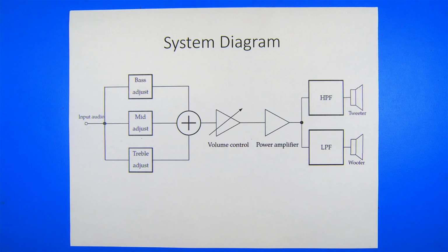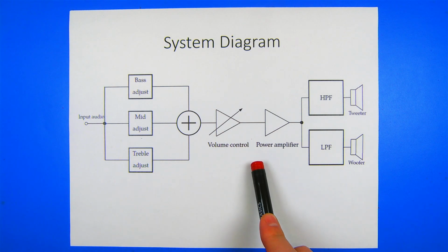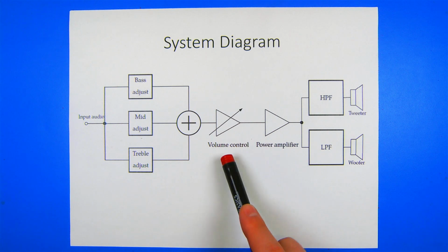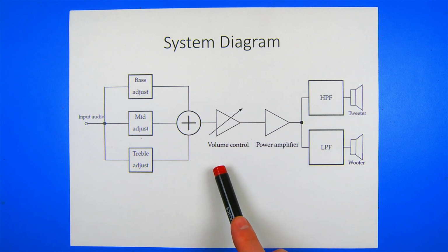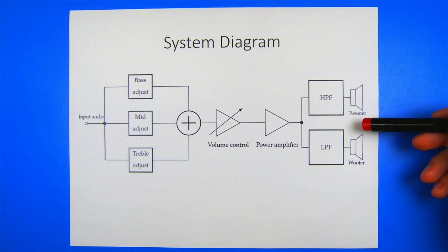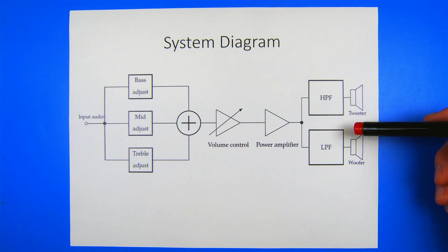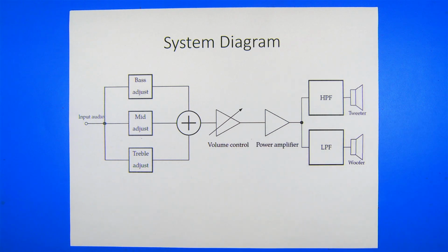Shown here is the detailed block diagram for the audio amplifier system. Applying many of the suggestions given in this video, for example, considering the maximum input levels for the power amplifier when designing the volume control, or using the pre-provided formulas for the inductor and capacitor values in the optional crossover from the lab manual, or furthermore considering using buffers where necessary, should help your designs be successful.